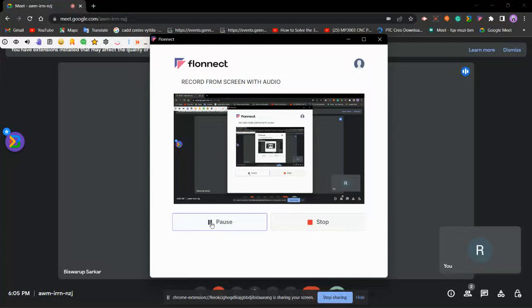There are different types. If the option is dimension, I can give length. If it is up to next and all, I hope you remember those things. I will show you that also. Then here we have to select the profile. If we have already drawn the profile, just select it from here.